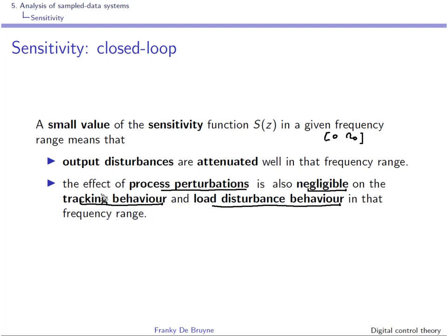This is just what we have seen. Okay, the sensitivity function is really the sensitivity of the transfer function PC over 1 plus PC when P is varying.